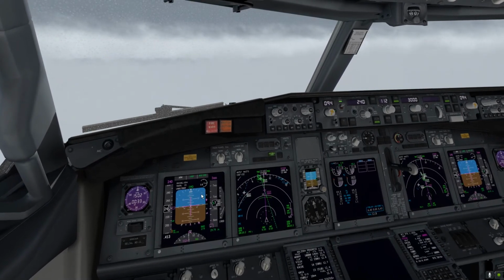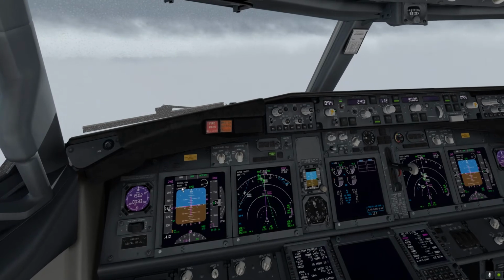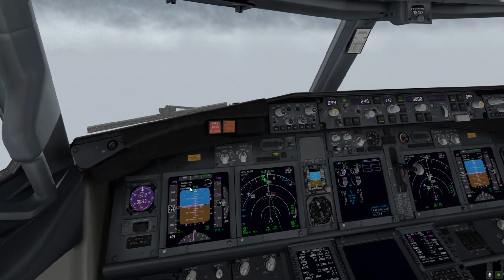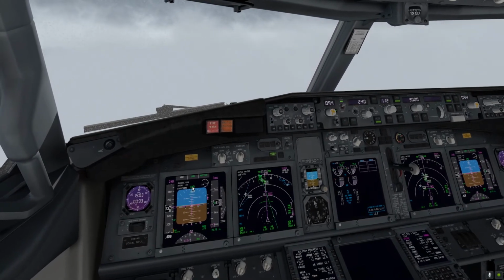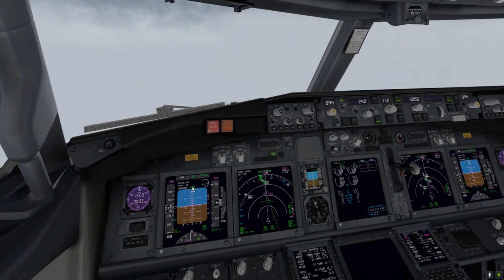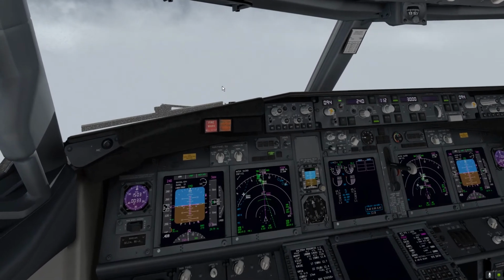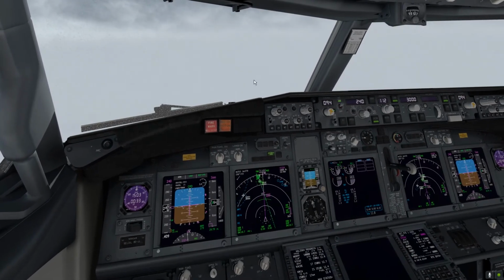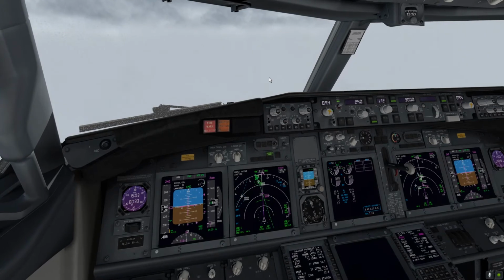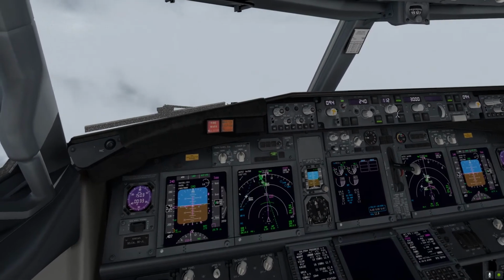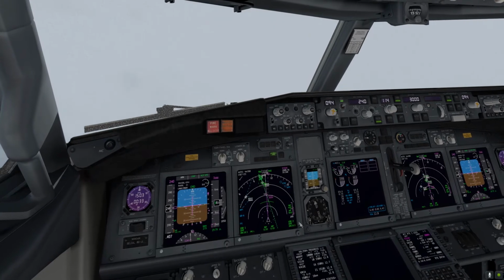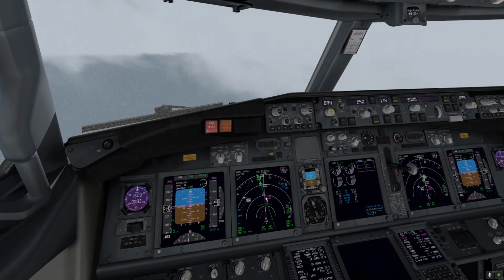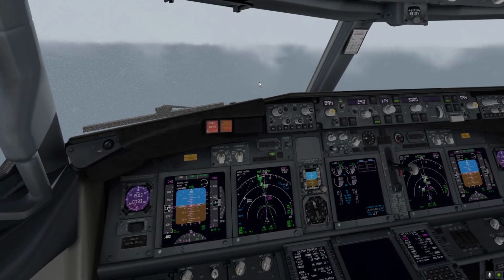So as you can see, the aircraft has already identified the type of approach we're going to fly, RNAV 08 left with final approach course of 094, which is double checked, and we are 21 miles out, which is really good. We're still doing good on profile, still keeping quite high speed and recovering, and of course we need to go back to the profile in order to lose speed later on.